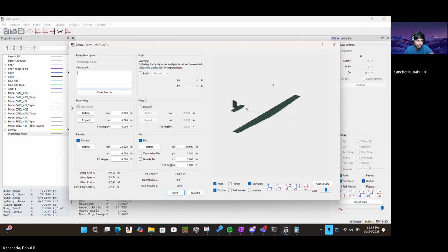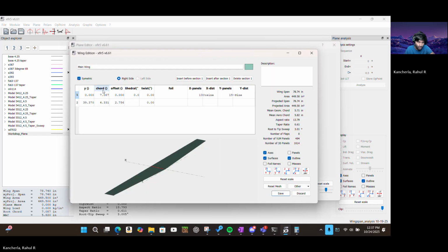And then, so first we need to assign a main. Let's see here. We decided 12 inches, right? So when you enter the span, so y in parentheses, it's along the y-axis. You want to enter half of it, because it's counting from the origin in one direction, but then it overlaps in another. So I'm going to say 6, right?